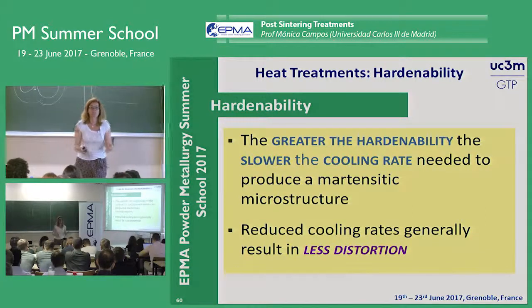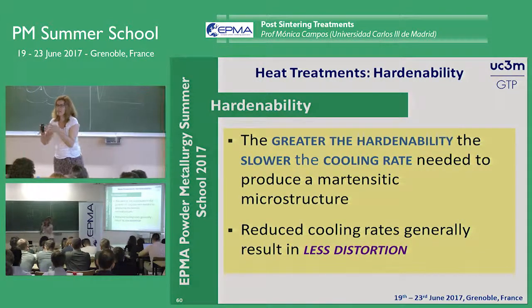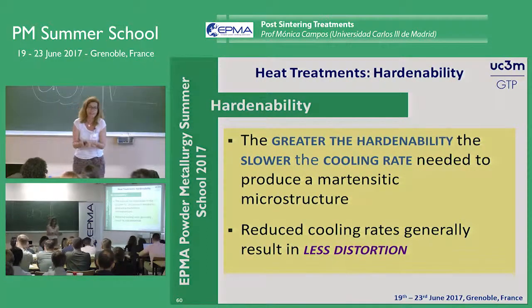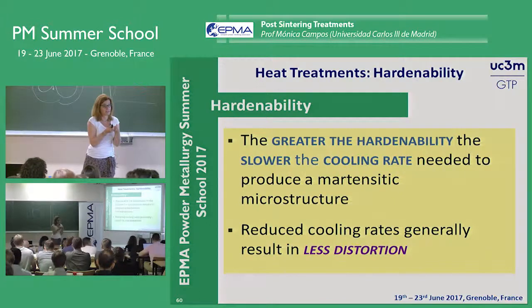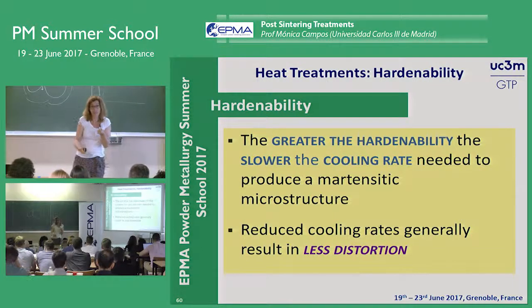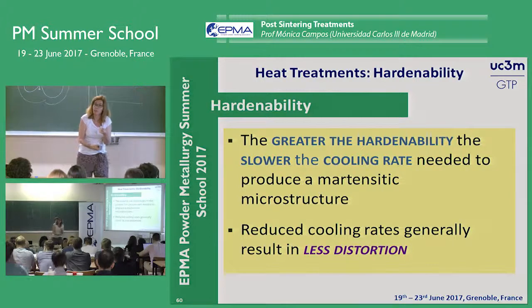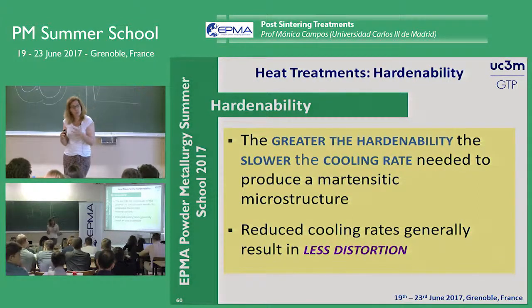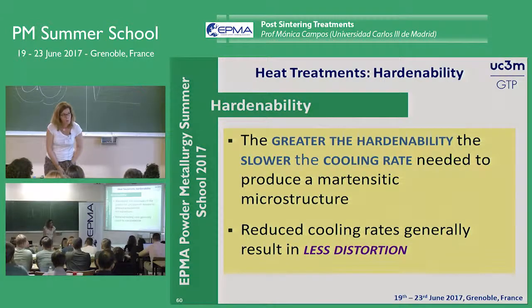Because heat treatment at the end means distortion. And then if my material has a certain level of hardenability, the environment that I need to cool down the material is not as severe as if my material did not have this hardenability level. And then the level of distortion is relatively lower.